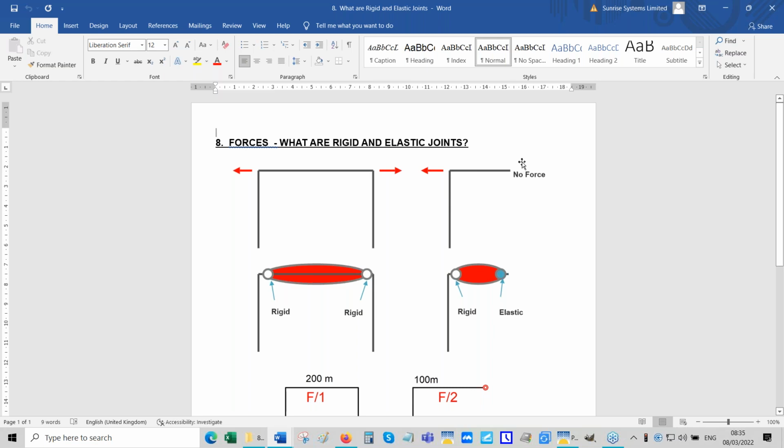And PIPENET doesn't know where they are and what compensating force they're exerting. That's one point that sometimes causes people a great deal of concern, because it's very clear that here the unbalanced force is the difference between these two forces, whereas here, the unbalanced force is simply that one component. So here, the unbalanced force would tend to be much higher than the unbalanced force here.